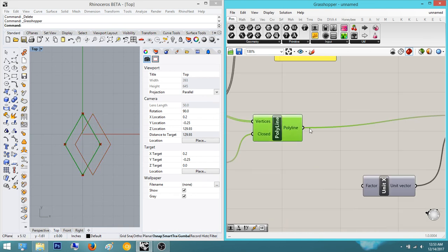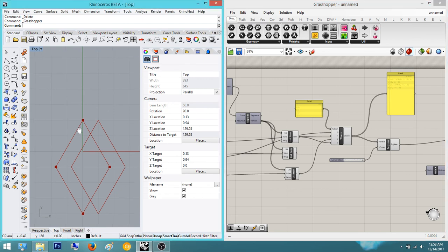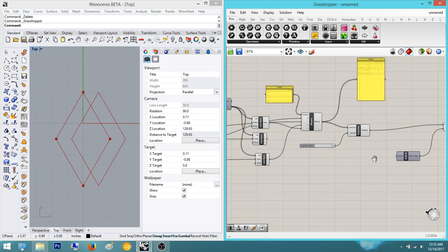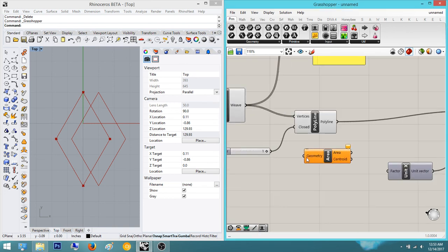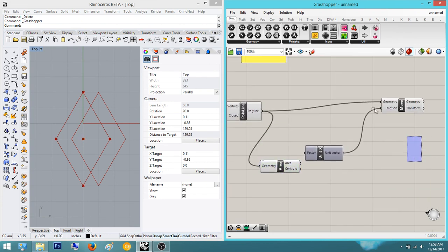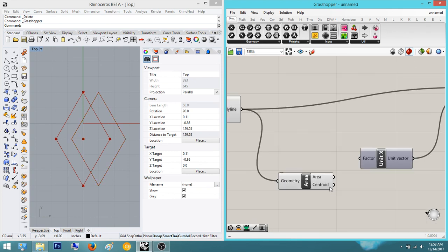Oh, also the reason why we did a polyline is, now you're thinking, hey, this is way more complicated than it should be. You could have just taken these two segments from your list item and these two segments from your other list item and just joined the lines. Grasshopper doesn't read that as one closed surface, or closed line geometry. So when you try to do an area command, it doesn't work. I think maybe polygon center would work, but I have not tried that. So the way I went around doing this was to do it by polyline, so the area command would work.